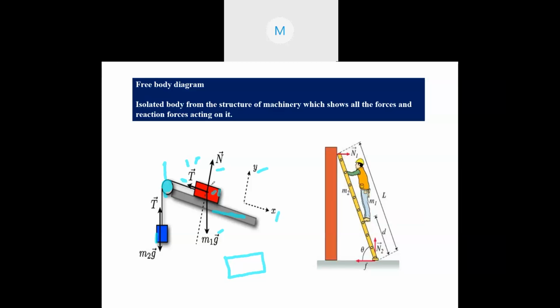Okay. Now everybody has a normal reaction, and the normal reaction always goes perpendicular from the body to above. So this is perpendicular from the body. Look at this. The body is inclined a bit, no? So from here it is 90 degrees. So it is 90 degrees from here. So this is the normal component.